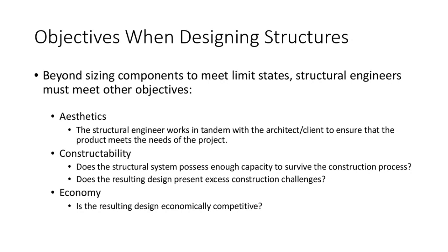A real world example: take some of the curved box girder bridges that serve as the overpass interchanges in Charleston, where 64 and 77 and 79 all meet. Some of those structures' worst case stress state is not when the structure is complete, but actually during construction, when it had 8 inches of wet concrete on it and the concrete wasn't composite with the deck. So it's one of those instances where if it survives construction, it'll survive its design life. So you have to understand that process.